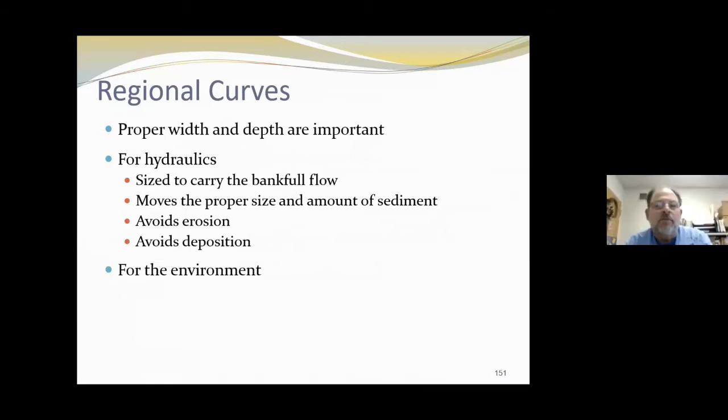All right. Generally speaking, in a step pool system, you're better off trying to find a section of that stream to survey and get a typical cross section of, to match it if you have to repair any damaged areas on a step pool system, rather than using the regional curves. And you have historical data, so you should already know what type of stream you're working in when you're doing the repairs. Excellent point. Thanks again, Mike.